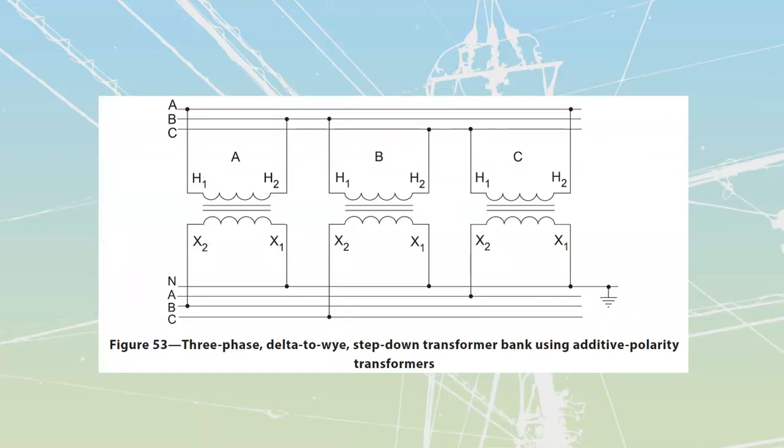did over here, where we had all of these connections through all of the X1s, the high voltage side, standard, the X1s connected to the neutral, X1s connected to the neutral, and X1s connected to the neutral. And then we saw that the C line was feeding A. We saw that the A line was going to be feeding B. And we saw that the B phase was going to be feeding C, like that. And so we had all of our connections in.